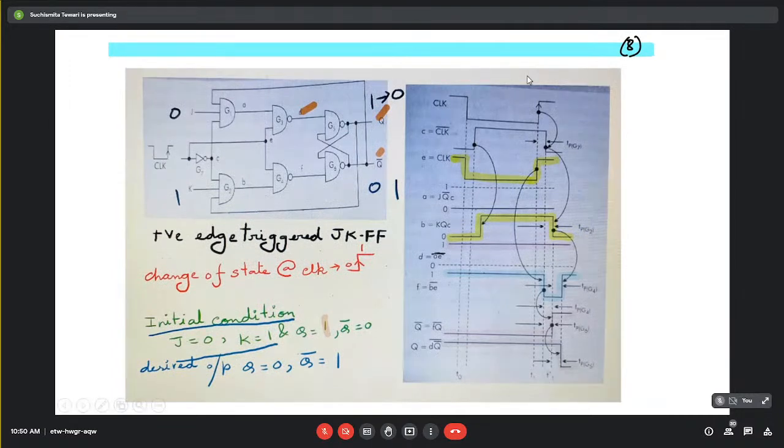Now this is the last problem today that we are going to study. This circuit is given, and here for the first time we will see the effect of delay. That is the delay through a gate, the gross delay, the propagation delay from input to output through a gate. It is not the gate delay that corresponds to the gate of a MOSFET. That is not the one. It is the gate delay at circuit level, whereas the other is the device level gate delay.